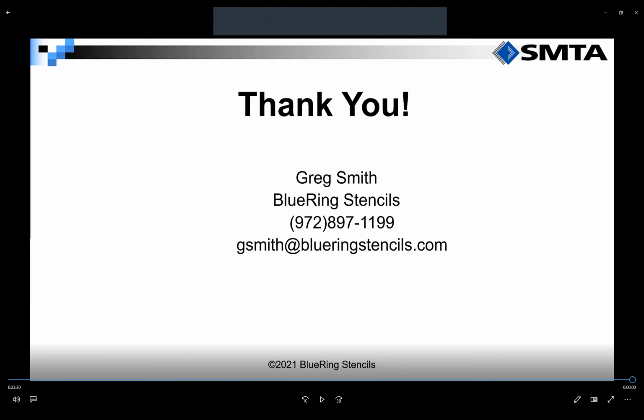Then mask defined pads become very critical, because at some point the PCB manufacturer can't hold certain sizes, like you said, plus or minus whatever it is, 20%. Whereas if you mask define those pads, they can leave those pads larger, and then they can define the pads with the solder mask process. So, whether it's direct imaging or whatever process they're using, that can become a more accurate way of controlling that